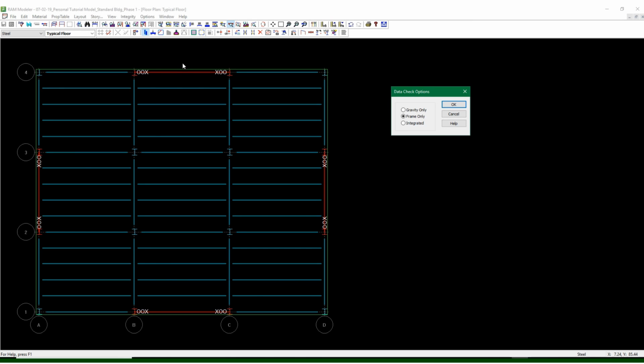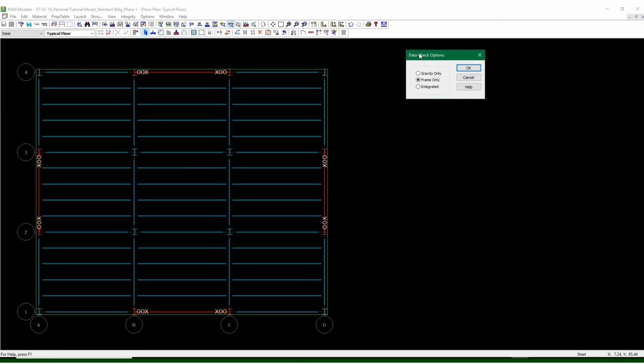And possibly an additional 4 for the beams because they don't have user assigned members, but they might have had the size that was selected from RAM assigned to them by default just as well. But typically you would get errors for these if you don't have user assigned properties for them.